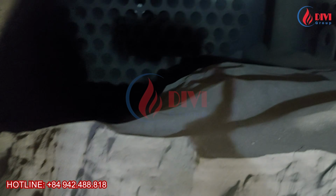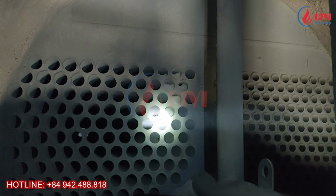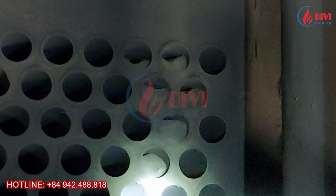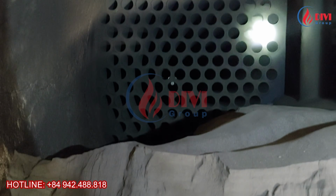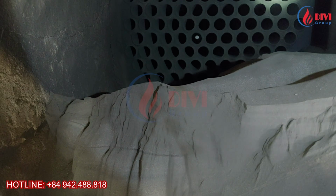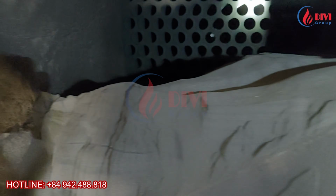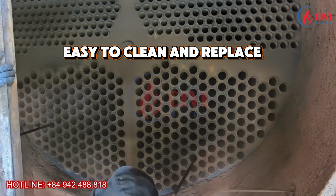However, it also has some limitations. Since the flue gas flows inside the fire tubes, ash and dust can easily accumulate on the inner tube surfaces. When burning biomass or coal with high ash content, the fire tubes need to be cleaned more frequently. If cleaning is neglected, ash deposits restrict flue gas flow, reduce heat transfer, increase stack temperature, raise fuel consumption, and reduce steam generation efficiency. On the other hand, cleaning fire tubes is relatively simple and straightforward.